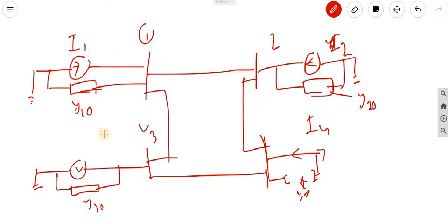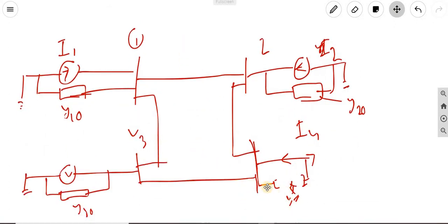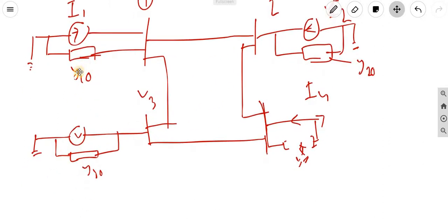So for the calculation of the network admittance, the load impedances are very high. As we know, the load impedance is basically very high, so that's why it is not countable in the network. Only the transformer, generator, transformer line, and supporting elements, suppose reactor and capacitor, the network elements, are considerable in the network configuration. But the load impedances are not considerable in the Ybus matrix.